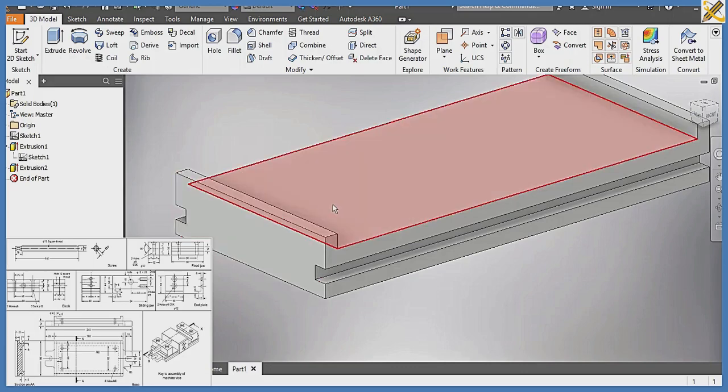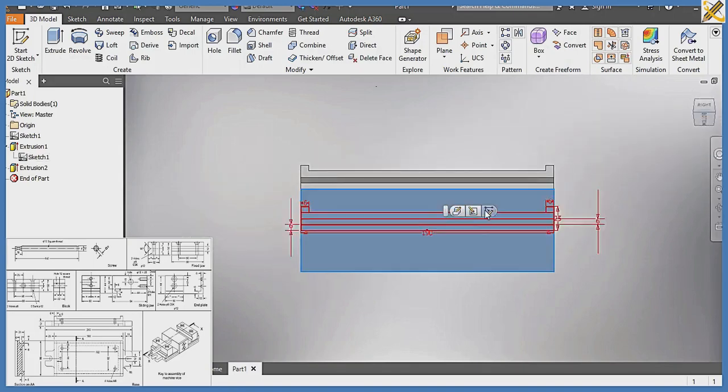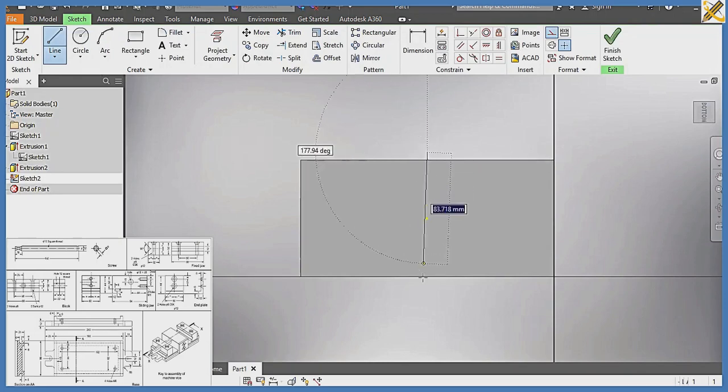All right, so having it in that order, what is the next thing to do? My next procedure is going to be this. Opening it to the back right here, clicking this back, creating a sketch right there. Before I proceed, I'm going to pick my hidden line. I'm drawing a line across in this way, then drawing another hidden line across in this way.